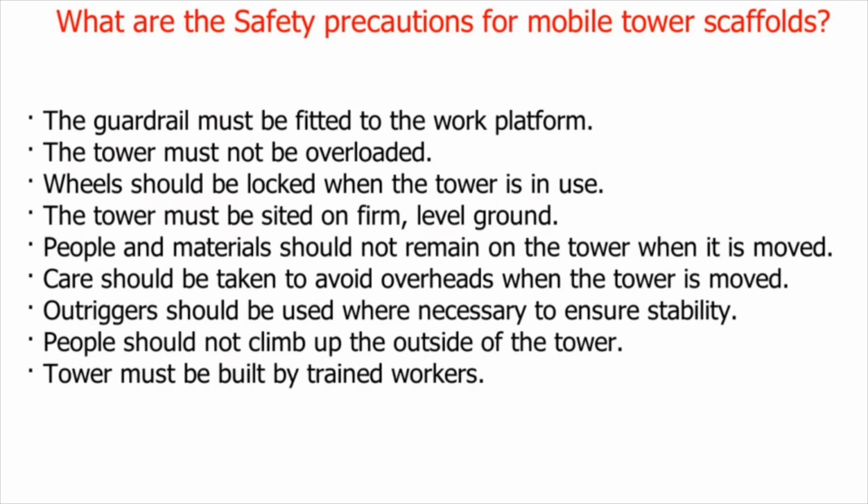People and materials should not remain on the tower when it is moved. Care should be taken to avoid overheads when the tower is moved. Outriggers should be used where necessary to ensure stability. People should not climb up the outside of the tower. The tower must be built by trained workers.